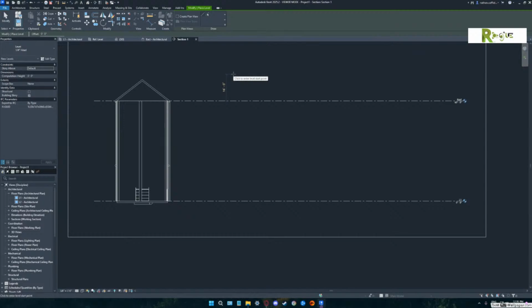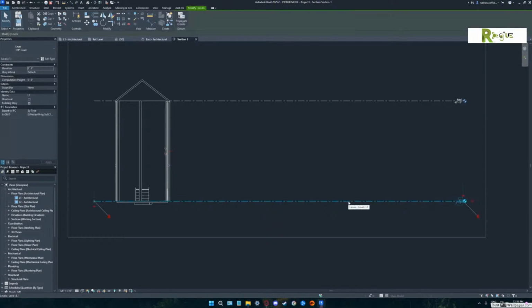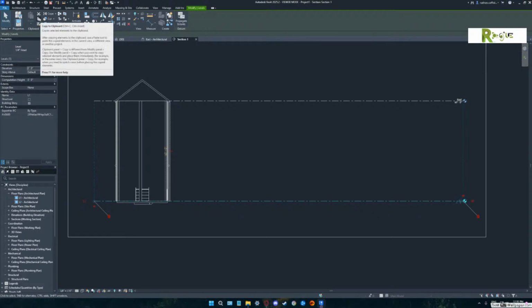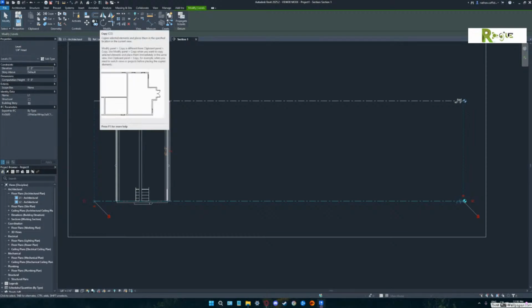So if you hit escape and went down and picked L1, you know where the copy command is? It's 2 over from the fillet command that we were doing to trim stuff up in the modify. Nope. Go closer to where the trim command was. Closer. Yep. Keep going to the right, down, and back 1 to the left. Oh, okay. That's the copy command.